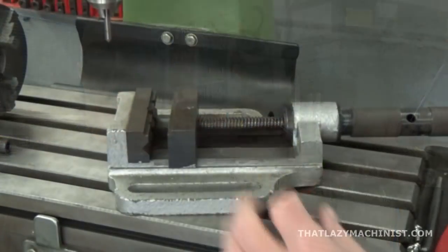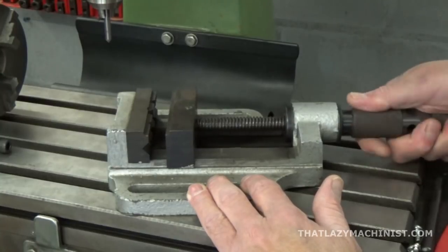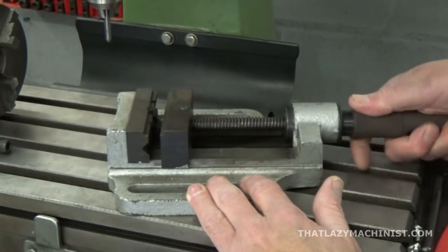The second reason that motivates us to use threads, well, there's another one that we're quite used to, and that is mechanical advantage, as we can see here with this machine vise. Now, a light amount of force applied on the handle gives a large amount or a great force applied on the part. And how is that? Well, our thread changes rotary motion into linear motion. And to the rotary motion, I can add a lever. And that's what the handle on a vise does.